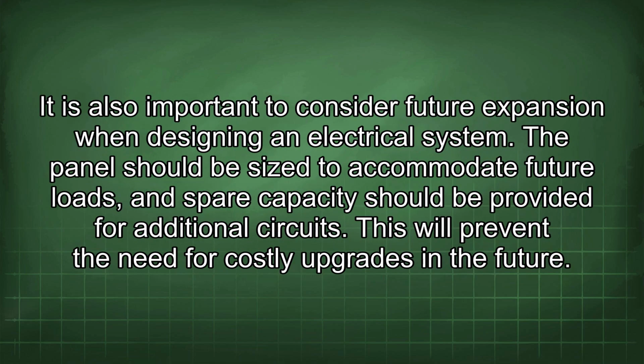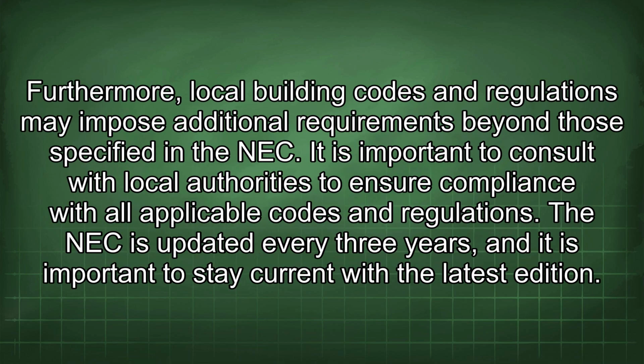It is also important to consider future expansion when designing an electrical system. The panel should be sized to accommodate future loads, and spare capacity should be provided for additional circuits. This will prevent the need for costly upgrades in the future. Furthermore, local building codes and regulations may impose additional requirements beyond those specified in the NEC. It is important to consult with local authorities to ensure compliance with all applicable codes and regulations.